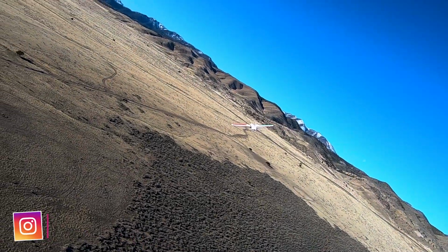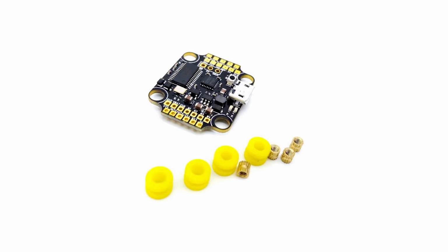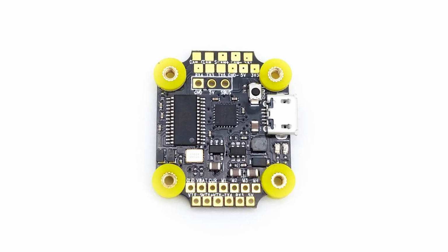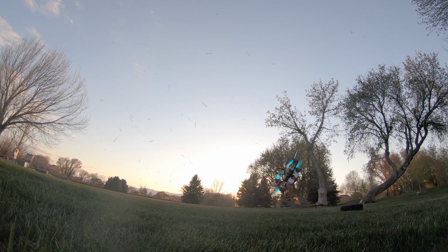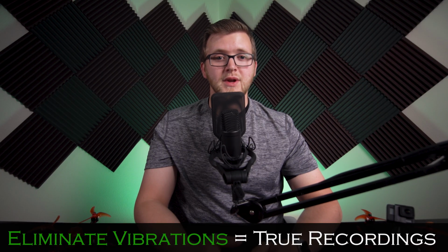A common practice used in conjunction with flight controllers is soft mounting. This is where you would include some kind of vibration dampener between the board and the standoffs. Because the standoffs are rigid, small vibrations from the motors can be transferred into the flight controller and cause the gyro to report messy data, which decreases performance. Adding these small rubber vibration dampeners eliminates these small vibrations and allows the gyro to read only the true movement